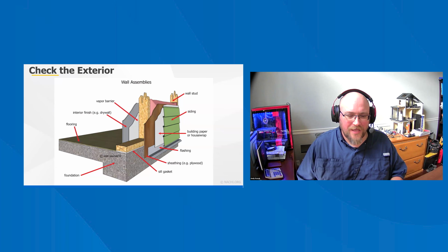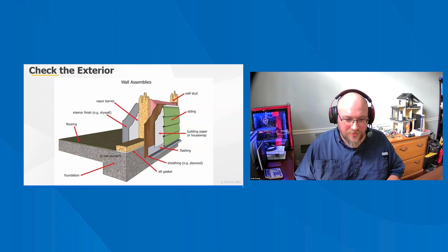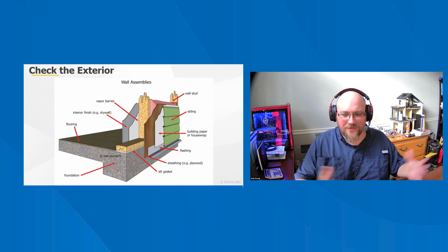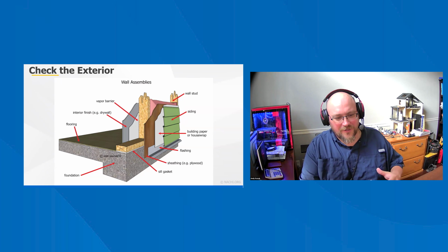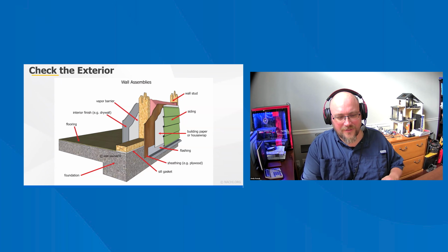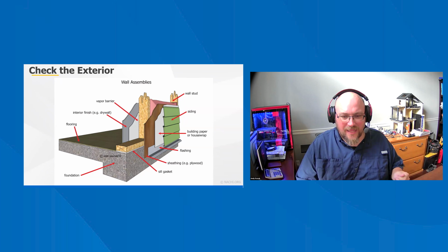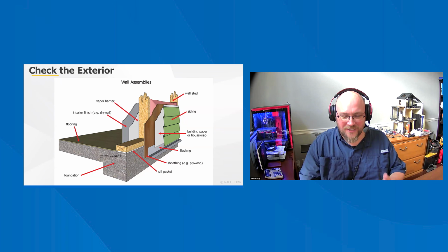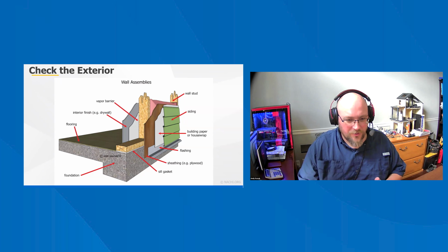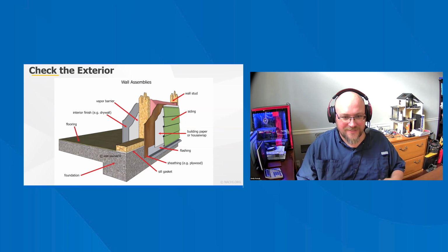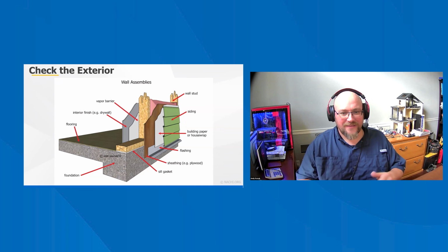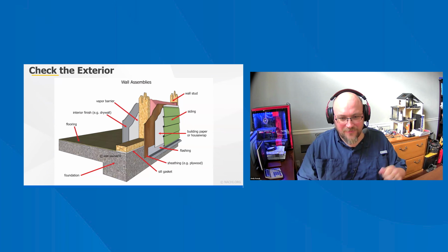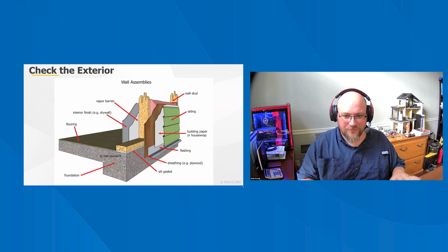And a lot of times, the builder, the contractor, they just buy a pallet of the ceiling tape, but they don't buy the flex tape, the stuff that was actually made to stretch and flex around penetrations or your window sills and that kind of stuff. They will just use that joint tape or that ceiling tape, and they will modify it around there.